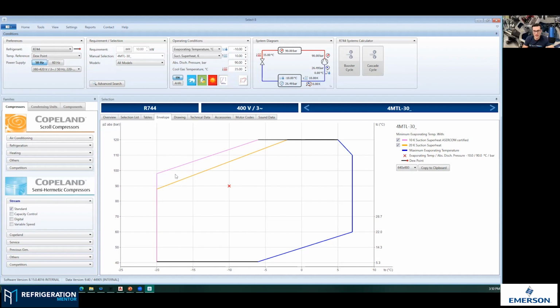Awesome. And so in this area, this top left corner of the operation envelope, I've seen this a lot before. I'm assuming this is where you may need head cooling fans, liquid injection, potentially demand cooling for compressors. Would that be correct? Yep. That is definitely that area.